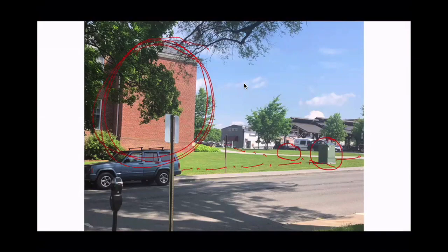But anyhow, assuming that this transformer is serving this building, likely there's now lower voltage power coming into the building here, and you would locate the switchgear right at the moment it went in the building. Because it turns out that burying power lines is expensive, and doing it in an inefficient way is dangerous too, because you don't want it going everywhere. You want to make sure it's protected. So generally, the side of the building that is nearest to the transformer will be where the power enters the building, and where the power enters the building is where those metal cabinets are.